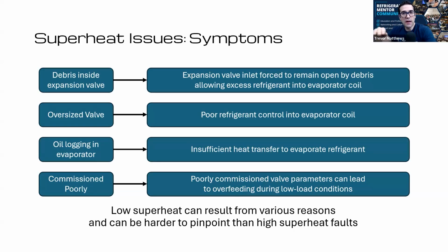And then all of a sudden you can start to see the temperature starts to rise up and the valve is starting to open more. So instead of it running around say 40 or 50%, the valve is running at 80 or 90% open now to try to maintain the same temperature. I find it so much easier to troubleshoot a case when you have all these checkpoints. Before, when I was in the field and on the tools, I had a set of gauges and I put it on one case and my temperature probe, and I had Cooper and say Yellow Jacket, and nothing was logging. So I just saw it at that moment in time. And I walk away, go to check another case, and then I come back and it's different. I'm like, okay, well, what's happening?